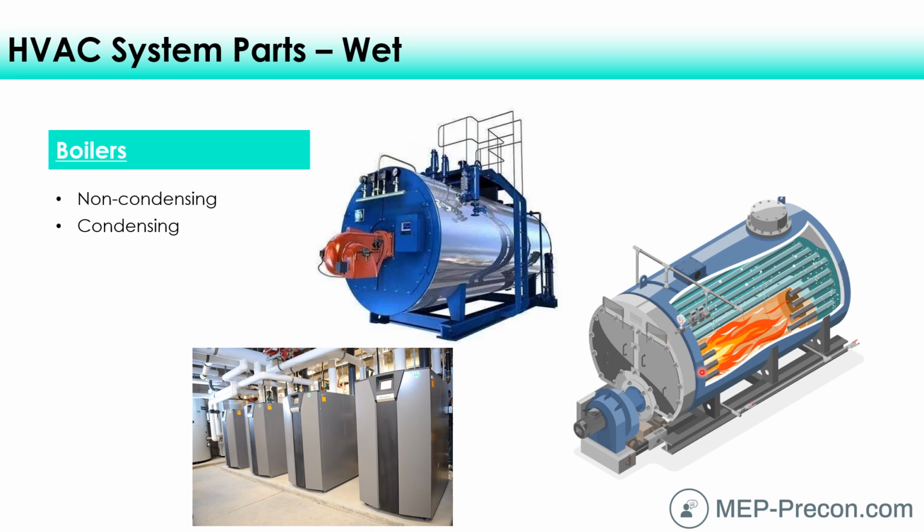That's where there's either fire tube or water tube boilers, where the flames either go through the tubes or the water goes through the tubes and the flames are on the outside. But that's how boilers exchange the heat between the flames and the water, within tubes. This is called a shell and tube heat exchanger. There's a shell on the outside and there's tubes on the inside, and the water and flames never come in contact with each other.